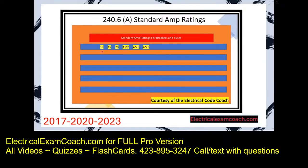And then it goes up by fives. 15, 20, 25, 30, 35, 40, 45, 50. And when we get to 50, it starts jumping by tens and even larger numbers as we move up in amperage. The reason that this table is so important is it unifies the entire electrical industry.